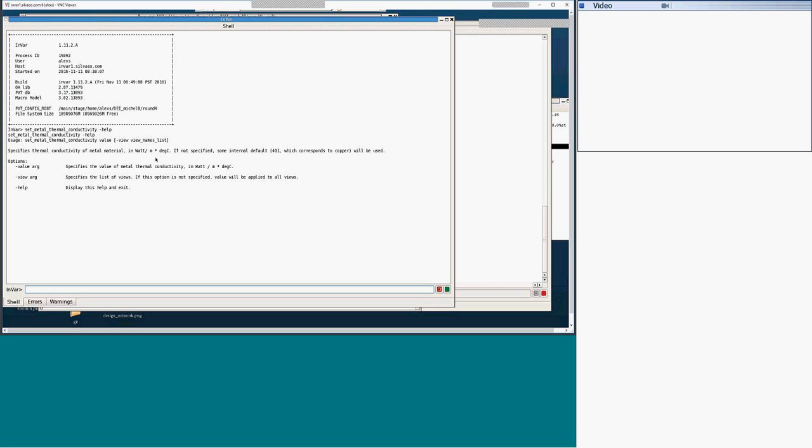Is that metal 1 or metal 2? So by default, it applies to all metals. This is like a setting for all layers that have type defined as metal, but there might be cases when you need to assign individual properties for individual layers. For example, your metal 1 is tungsten, and it would be different. So for more detailed assignment, we use the command set layer params.